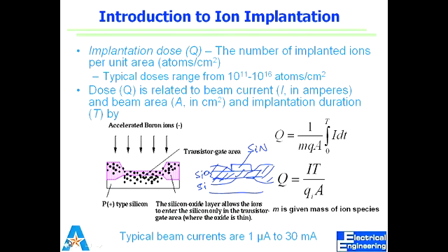which is striking the substrate from the top, and all we can control is how much reaches in a cross section, right? And then how deep they go within that cross section. Then the depth would be the third dimension, but that would be within the substrate now. That is not a function of the beam itself, but there's much more that comes into play once you talk about the substrate. So implantation dose is kind of a parameter for the equipment that we are using, of the beam. Simple, because the beam is striking a 2D area.